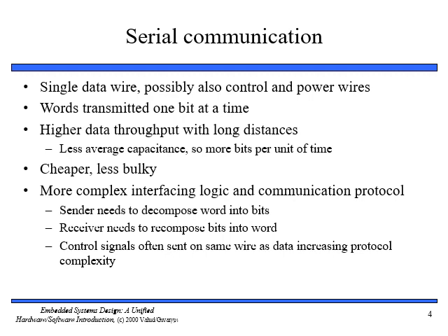The disadvantage of a serial bus is that the interfacing logic and communication protocol will be more complex. On the sending side, the transmitter must decompose the data word into bits, and on the receiving side, the receiver must compose bits into words. Most serial bus protocols eliminate the need for extra control signals, such as read and write signals, by using the same wire that carries data for this purpose. This is performed as follows.